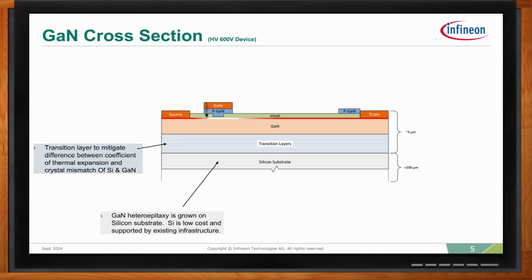But the real magic happens when aluminum gallium nitride, AlGaN, is deposited on top of the GaN layer. Due to crystal strain over nanometer distances, and these are very small distances, and the piezoelectric characteristics of GaN, a two-dimensional electron gas forms between the two layers, so that when an electric field is applied drain to source, current flows within the device.